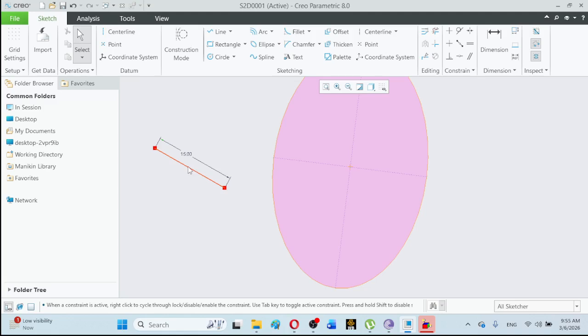this line and the third point: if the distance between the center of this line and the third point is greater than half the length of this line, then this line will become the minor axis and the other axis, which will be perpendicular automatically, will become the major axis.